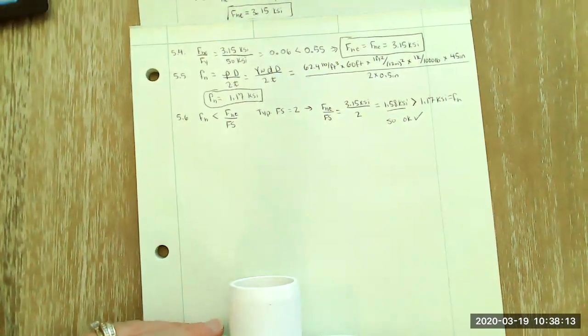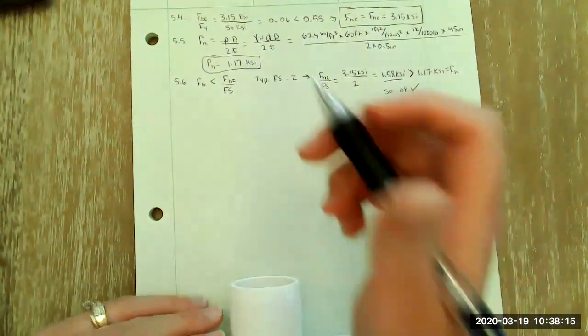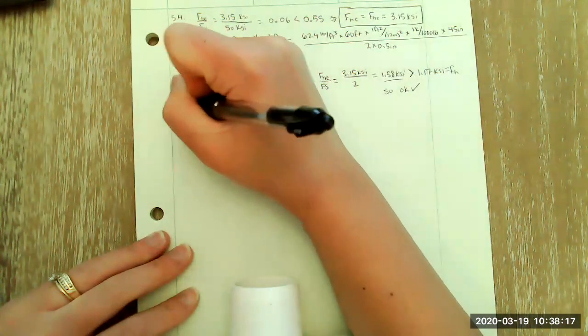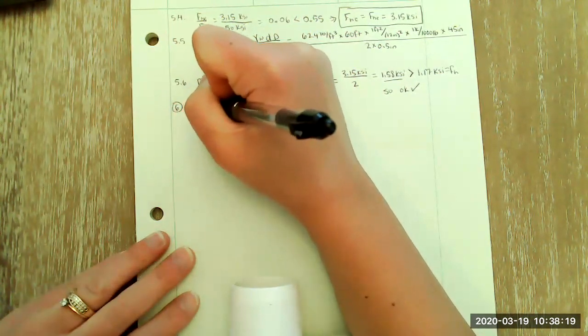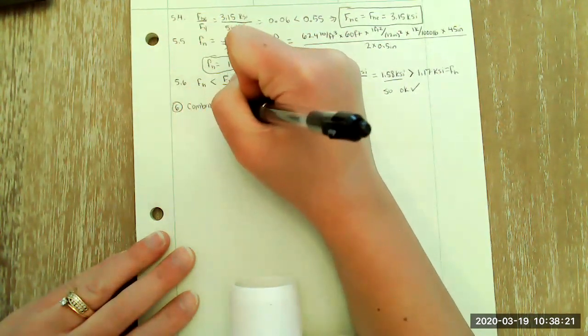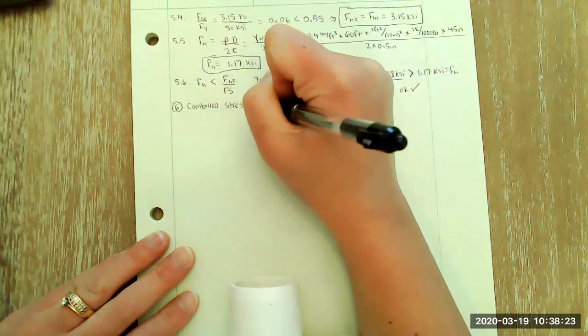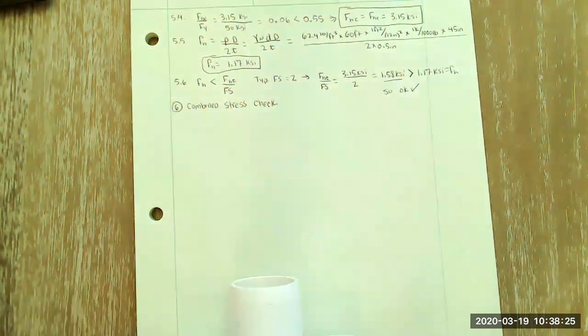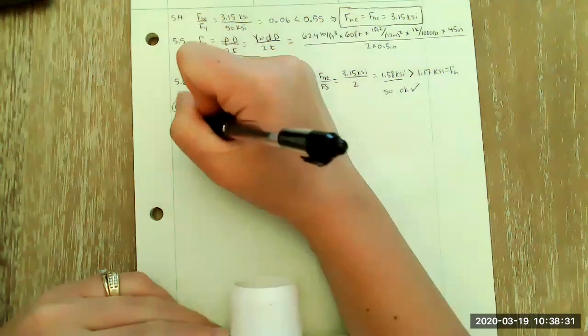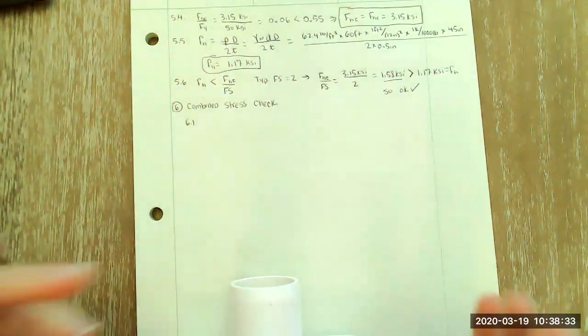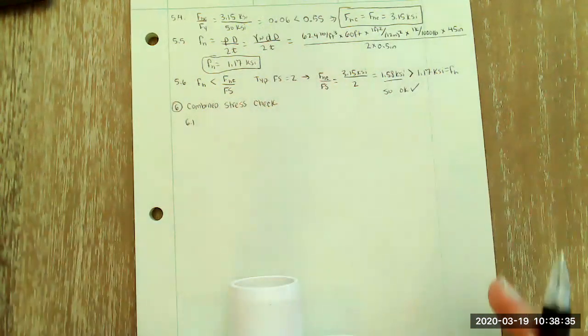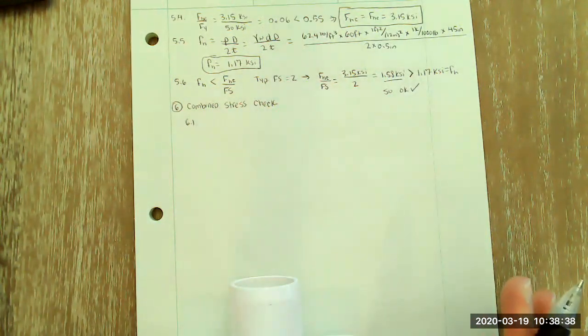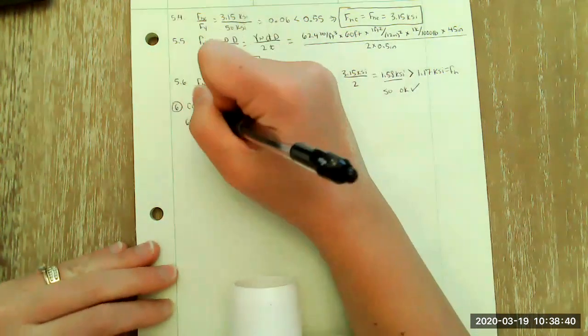So this is the very last step, step 6, our combined stress check. And again, here we're considering the combined effects of axial compression plus bending. Specifically, the first thing we need to do is see whether the P delta effect is important, whether that compressive load is so heavy that you might cause additional bending to occur.